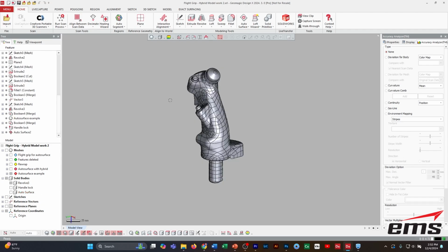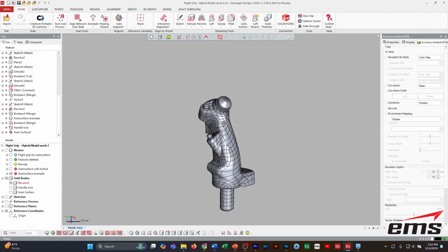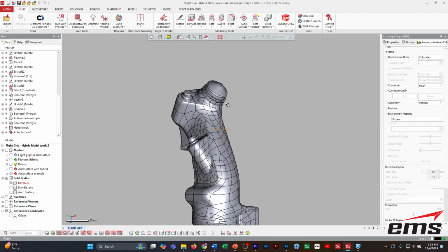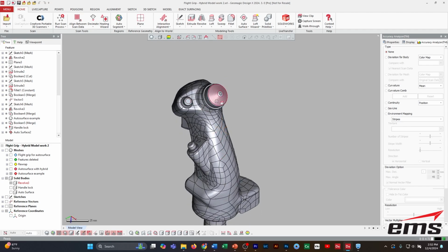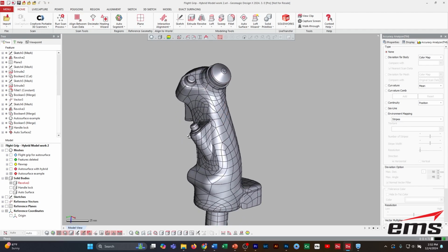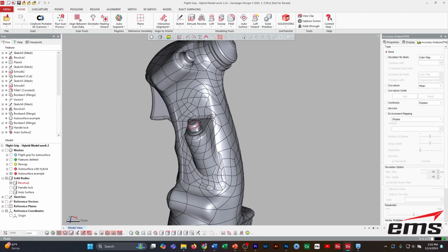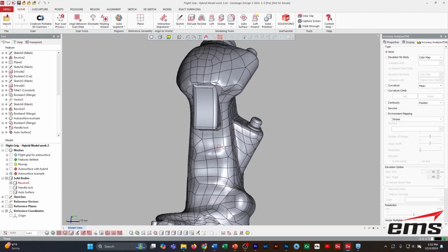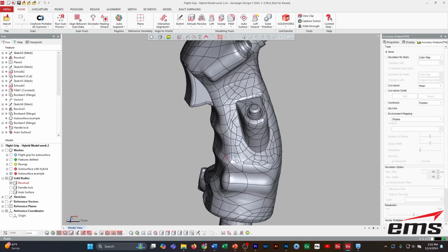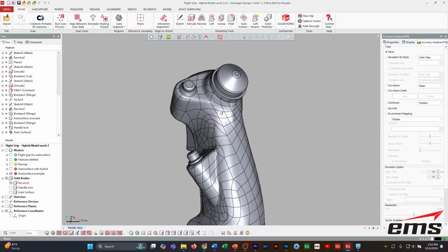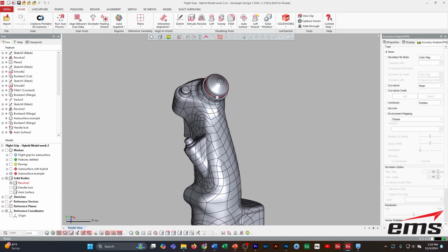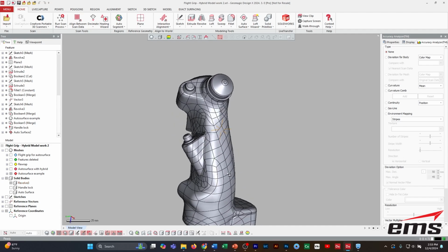All right, next, let's take a look at a hybrid. Now, we did go into hybrid modeling a little bit in that previous video I'd mentioned. And if you look, things are a little bit different, specifically some of these features. Okay, so these are more what we call sketch-driven or prismatic features. So the trigger and some of the buttons you can obviously see are different. This is a good compromise sometimes for somebody that needs to be able to edit the buttons or make changes, but the main body, maybe they don't need to make changes to.